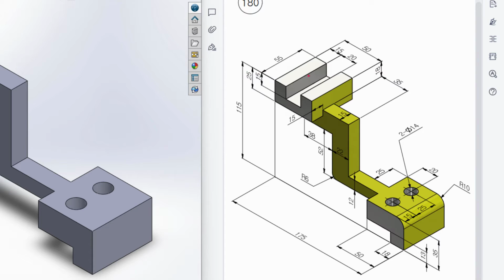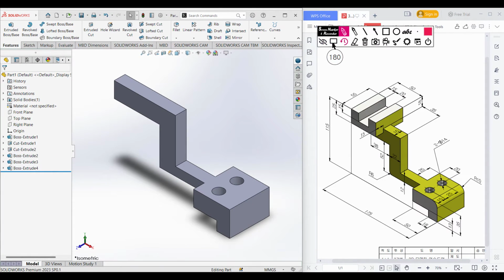Okay, so after that I will draw for this extrude cut rectangle. I will draw a center line here, and from the center line I will offset two lines. As the total distance is 20 unit, so the half offset will be 10 unit each. Then I will close the shape and draw a rectangle. Then I will extrude cut it to 15 unit. Okay, let's go back to our sketch and demonstrate it.